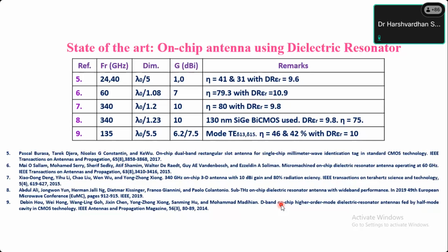So you can see here, generally in an on-chip antenna, the gain we are seeing here is 7, 10 dBi. That is not the common gain. In on-chip antennas, the most common gain is generally minus 20 dBi, minus 30 dBi. Even gains of minus 60, minus 50 dBi are reported. That is also accepted, because if you are not utilizing any technique to improve the gain and you normally design a common antenna, the gain will automatically reduce because you have reduced the size of the aperture as well as you are designing on silicon.